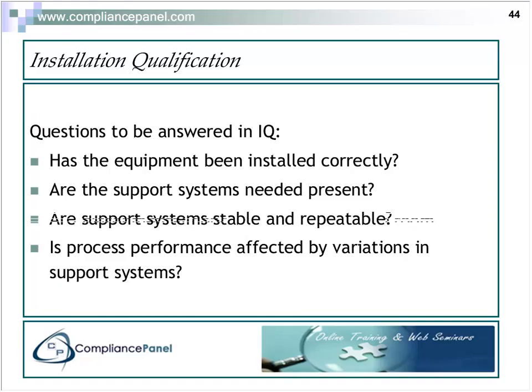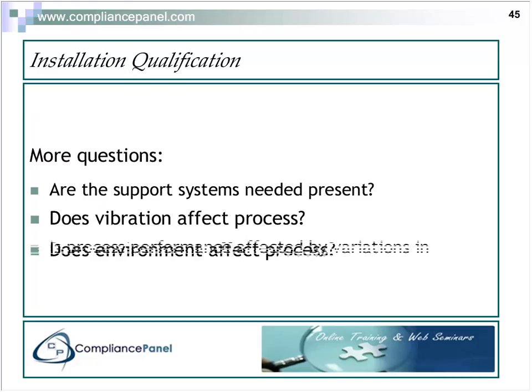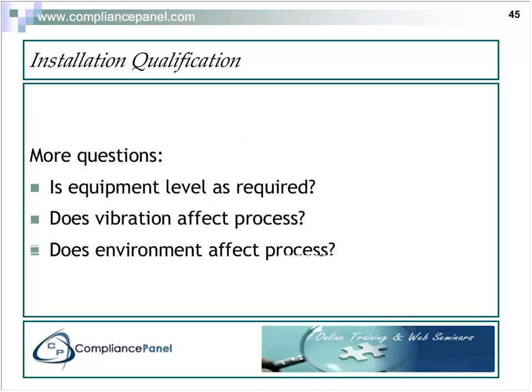And here are the questions at the end of IQ. Here's what we should be satisfied with. First of all, the equipment was installed correctly. Are the support systems provided and correct, stable and repeatable? Is the process performance affected by variations in the support system? So when the electricity varies, what's our result going to be? Is the equipment level as required?